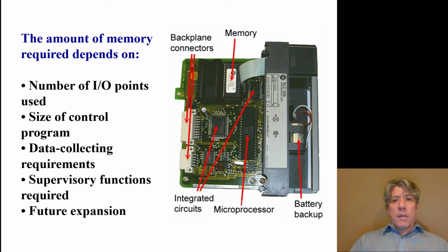Another thing that is important to consider when deciding how much memory you need in a PLC is future expansion. What might be added on to this later, where we don't really want to buy a whole new PLC? Also, how much communication has to be accomplished. The more communication, the more memory that's required. That's just part of communication. So all these things play into selecting how much memory goes into the particular PLC.